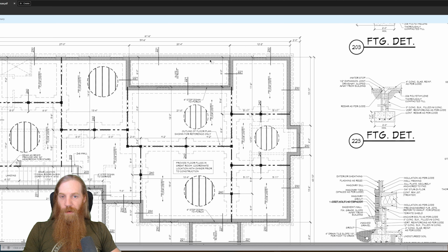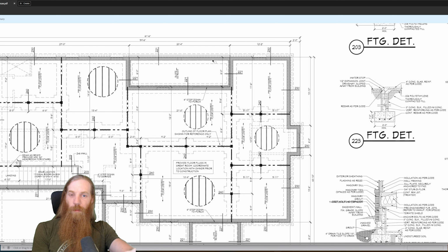And then I'm not going to do a foundation wall on the exterior. You could do a stem wall right there for your porch to finish on top of. This is for more like a poured concrete porch. Because we're going to be high up off the ground, like I was saying before, the main floor level is going to be about 4 or 5 feet above grade. Doing a poured concrete porch there doesn't quite make as much sense to me.